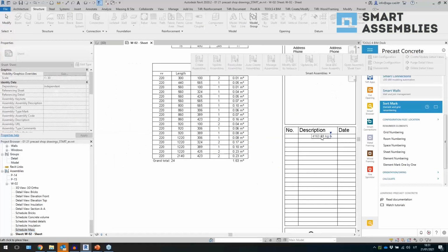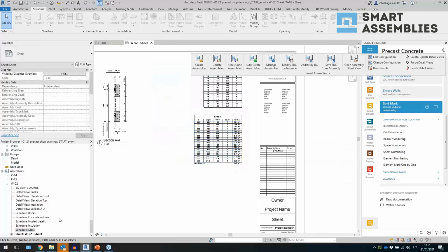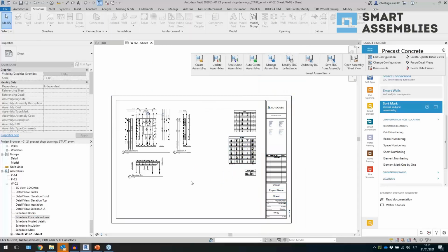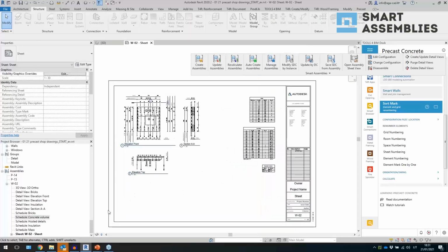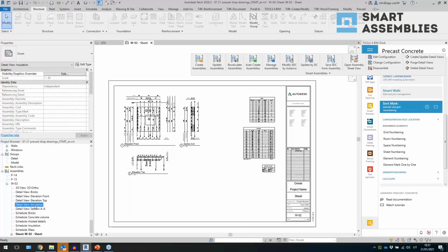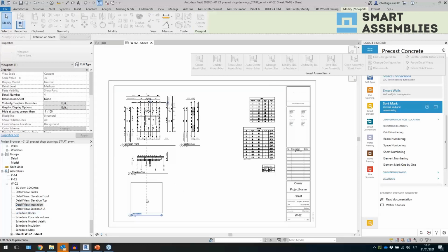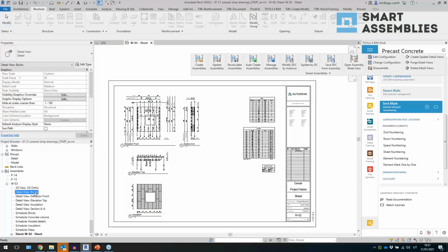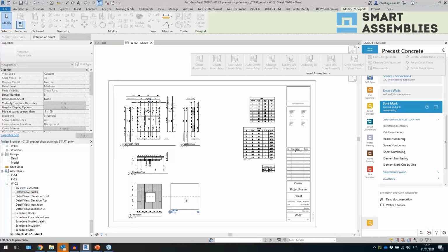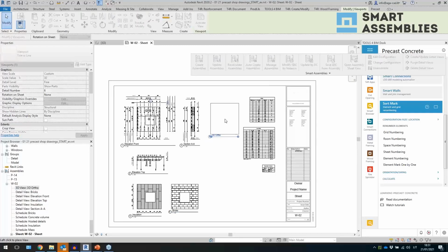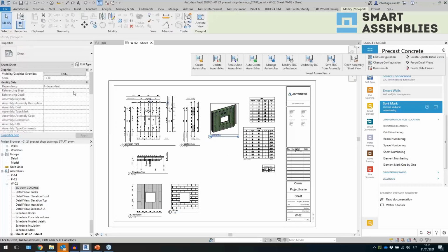So drop it here, and then let's say you'll spend 2 or 3 hours working on the configuration, right? So you will create view templates, you will create maybe dimension styles which you need, maybe you didn't have them. So different kinds of stuff you need to complete that, but I think it's worth it, because for every next panel it should save time for you, right?